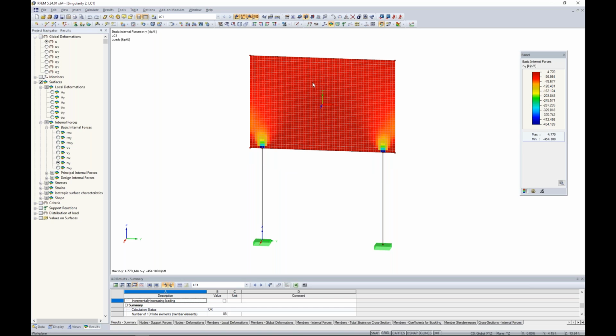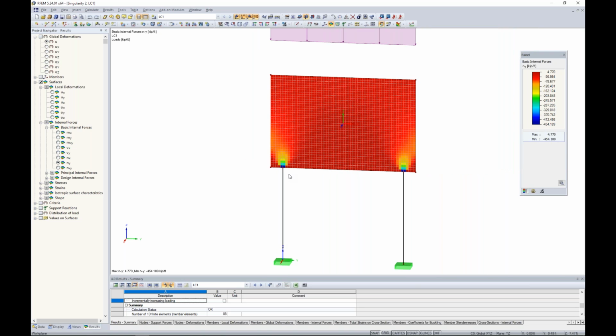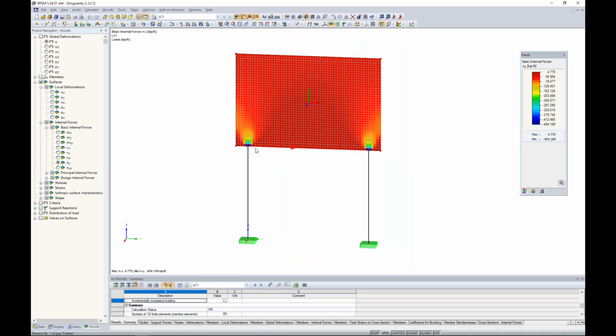forces, this is going to be compression and tension in this wall. We have extremely high peak forces here, you know, those singularities. We're seeing compression here at 454 kips. So this is definitely not ideal. So how can we see better load distribution over this area?